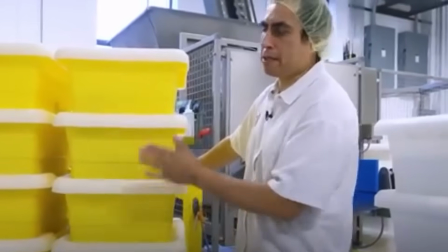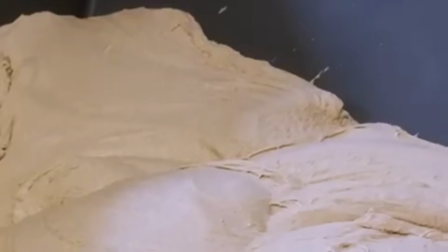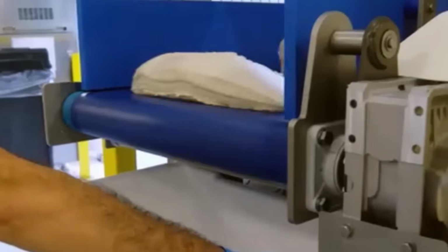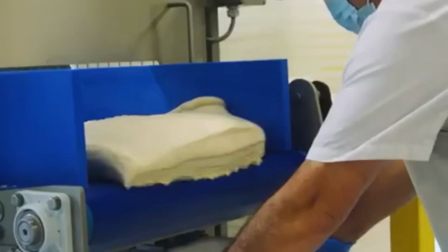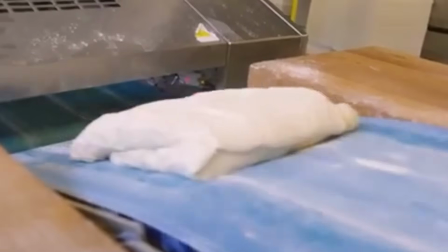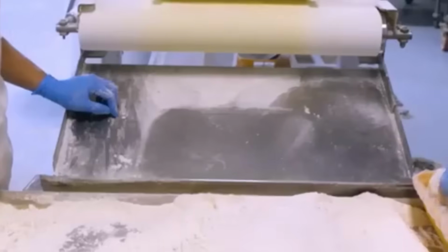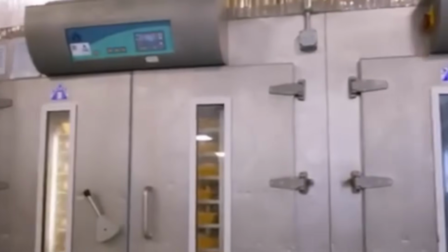A sheeter receives the dough next. Twin rollers compress it into a continuous slab, which then moves through a series of gauges to ensure thickness and density remain exact. This is not a shaping step, it's preparation. The flattened dough is directed into a high-capacity divider, where a series of volumetric pistons cut the slab into uniform portions. These pistons measure by volume rather than weight, ensuring that even as humidity or temperature fluctuates slightly, each piece contains the exact same mass of air and dough combined.